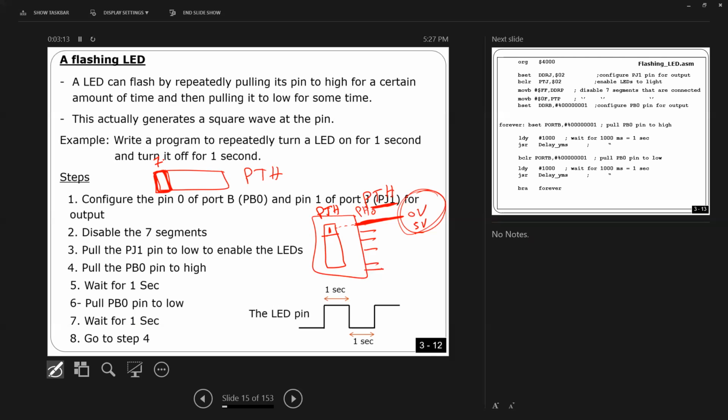Very easy. I explained in assembly, you can use branch if clear, you can use branch if set, as I explained before, or you can use AND operation also. So you can use AND operations. You can put 1 here and 0 everywhere else, as I did. Here you're going to get bit 7, and then 0, 0, 0, 0, 0. If the result is 0, that means this bit is 0, otherwise it is 1. That's how you check.